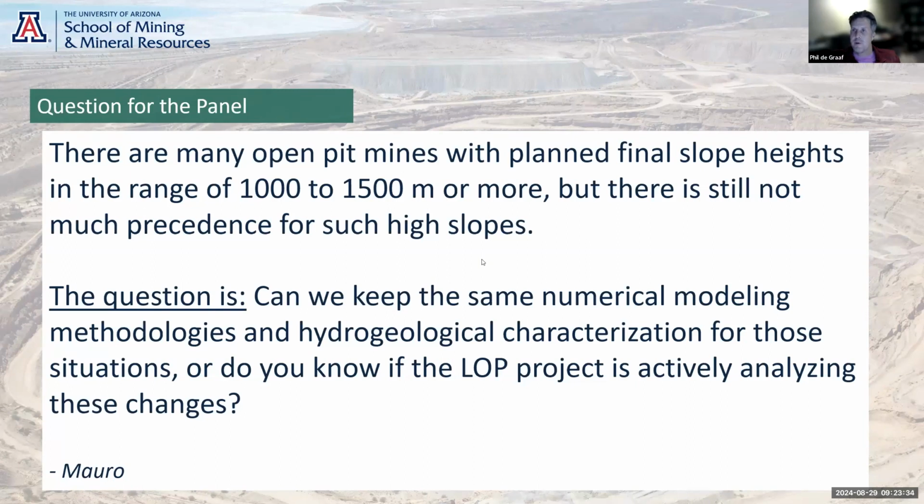You probably wouldn't be messing around with any limit equilibrium analyses. You're certainly into numerical modeling, 2D and 3D models with, like John mentioned, a lot of instrumentation to back it up, and the consequence will help pay for all of that extra rigor in the process.